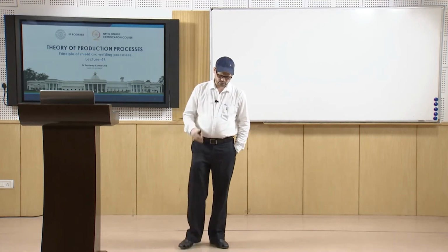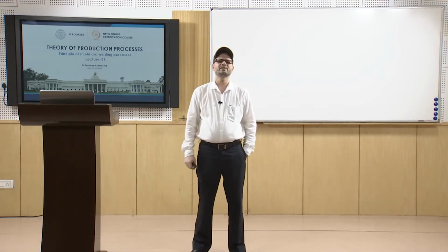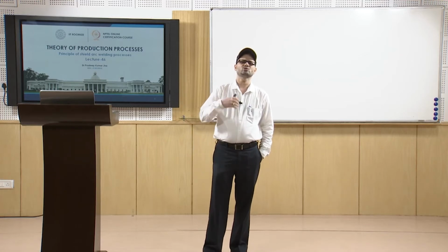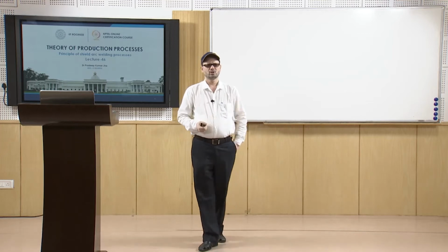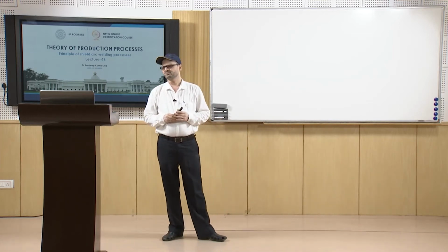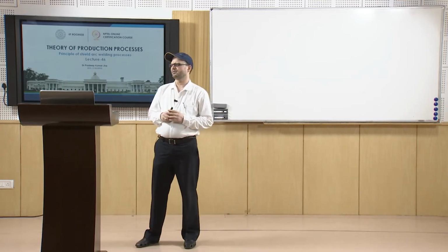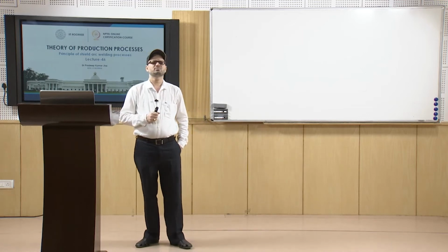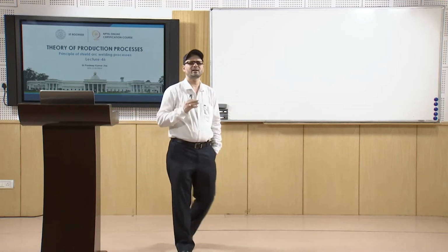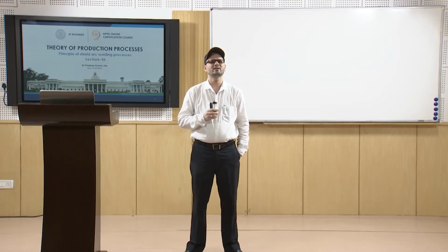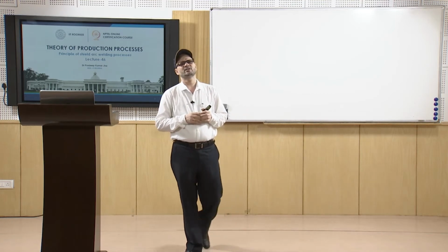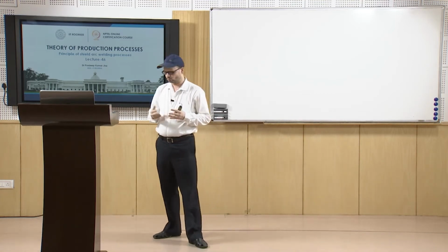Now, we come to the first variety of shielded metal arc welding. This is also known as SMAW. So, what is there in that? Coalescence of metals is produced by heat from electric arc, which is maintained between the tip of a covered electrode and the surface of base metal in the joint being welded. So, that is how the SMAW takes place.